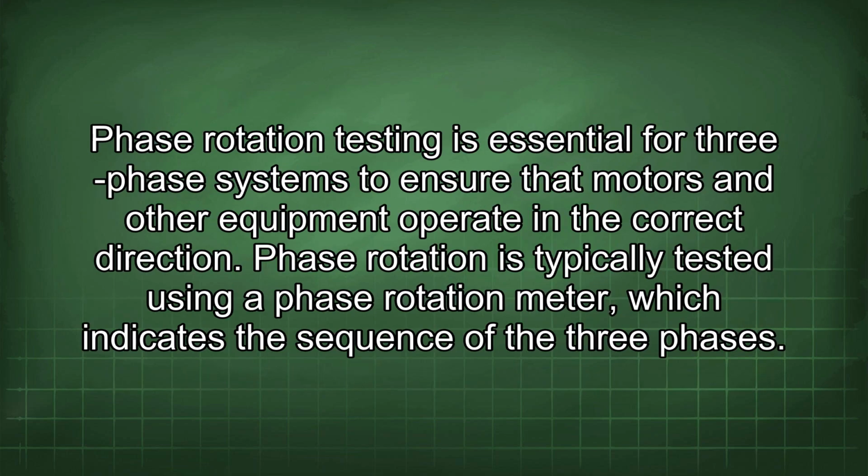Phase rotation testing is essential for three-phase systems to ensure that motors and other equipment operate in the correct direction. Phase rotation is typically tested using a phase rotation meter, which indicates the sequence of the 3 phases.